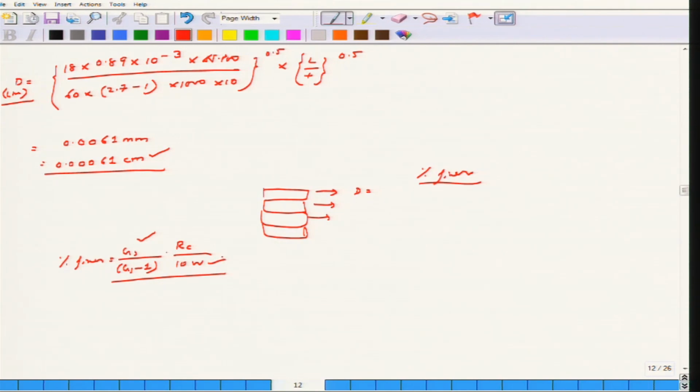W is a very important part, because W is said to be the percentage of the soil mass that is taken. Let us say that the weight retained in the pan at the end is 240 grams. Out of the 240 grams, suppose you took only 40 grams for hydrometer analysis. That 40 grams is to be immersed in 1000 ml of the liquid.